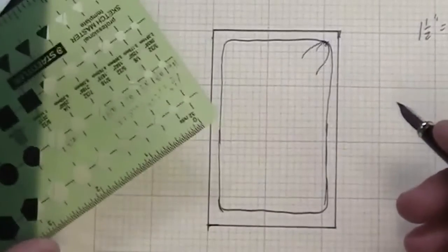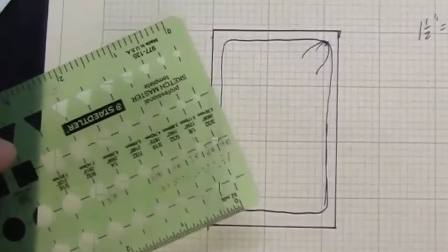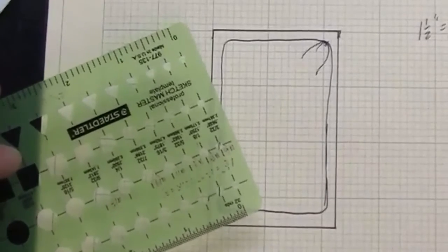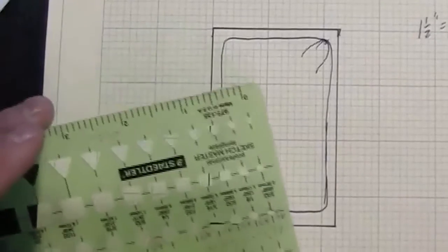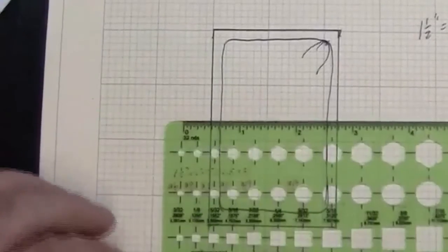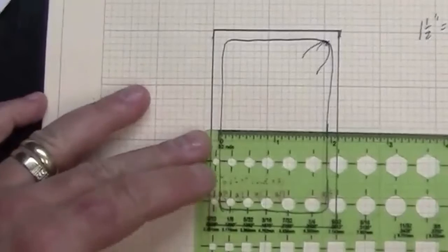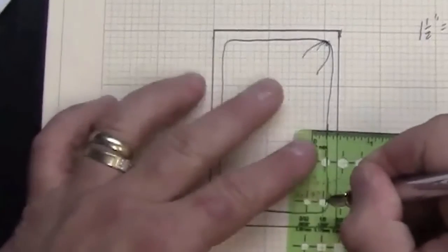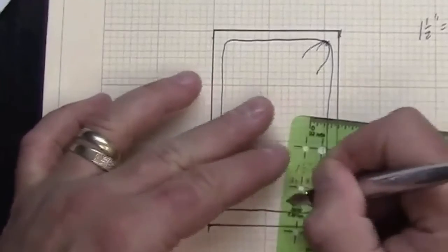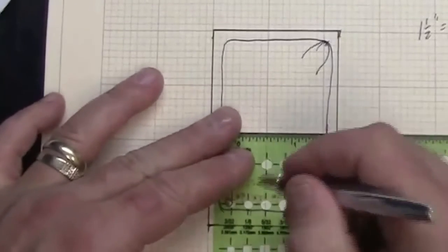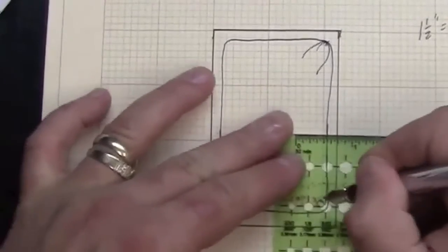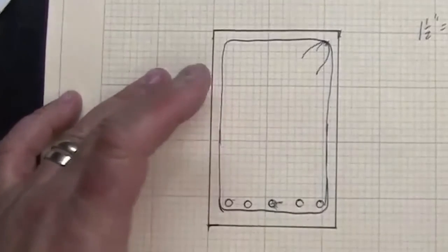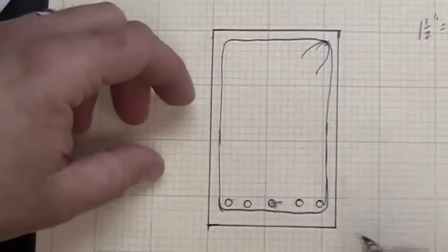That's starting to look something on the order of 5 number 8 bars, and I'm going to just get a feel if that will even fit. And I think it will. If I look at my bar spacing graphically, it looks like I can fit those in without too much trouble.